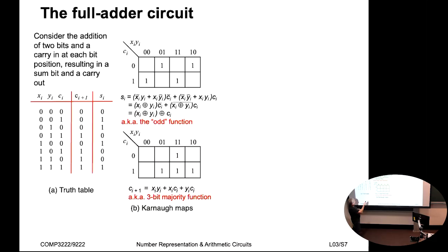And so then we're left with exclusive OR and Ci bar, or not exclusive OR and Ci. So it's the same as A bar B or A B bar, which is just exclusive OR again. And hence we can see that this is just the exclusive OR of all three variables. And we can show by associativity that it really doesn't matter where those parentheses are. In fact, we don't even need the parentheses.